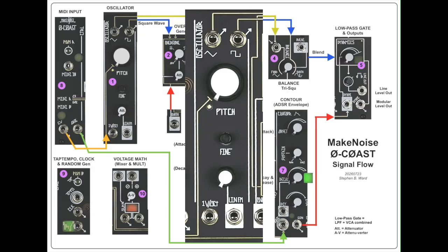Now, the native or core waveform of this circuit is a triangle wave. But you can compare a triangle wave as it goes up and down to 0 volts. And if it's above, you can have a high output. If it's below, you can have a low output. So you can create a square wave and derive that from the triangle wave.